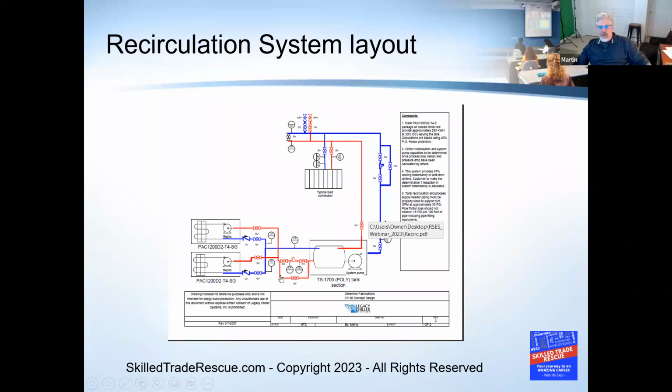We would equip these, I don't know if you guys are interested in this, but we'd always equip these things with filter bypass assemblies. Or we put this in the design. We didn't do plumbing, we just did the manufacturing, but I always provided these designs to my clients. And this gave them the ability, we had pressure gauges we recommended installing across these strainers. And when the pressure differential across the strainer got too high, they can close these two valves, open this valve, clean the strainer, and put it back together again. This is a basic filter bypass assembly.